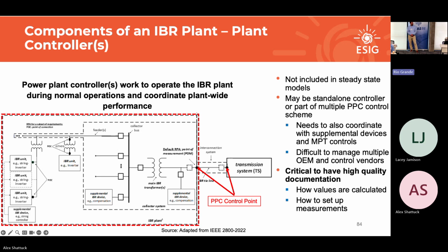A little bit more about the multi-PPC control scheme. I've seen that in more models, and I thought it might have been an error. But is it essentially one behaves as master and the other as slave? It could. That's one of the reasons why EMT is good, that you can model them however they're connected in the real world. A main-secondary hierarchical control is one method that people use. That's what I would use, because then you have one measurement point, one plant controller doing the math and just sending signals to the other one, which is sending it to its inverters.